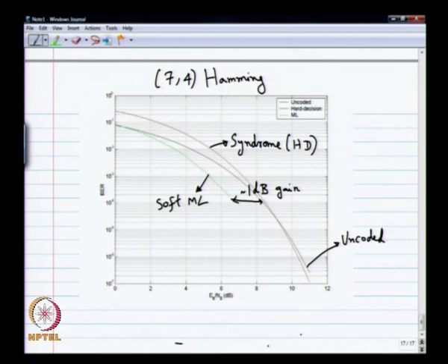That happens to be a very expensive component, and if you can reduce the power of that by 1 dB, the price will go down by several tens of thousands of dollars. You can imagine that. So, it's a big reduction in price. Coding gain really buys you a lot of things. 1 dB is not bad, but if you are giving up 7 dB, maybe you should think about it. Maybe there is something more I can do to gain from the 7 dB loss.